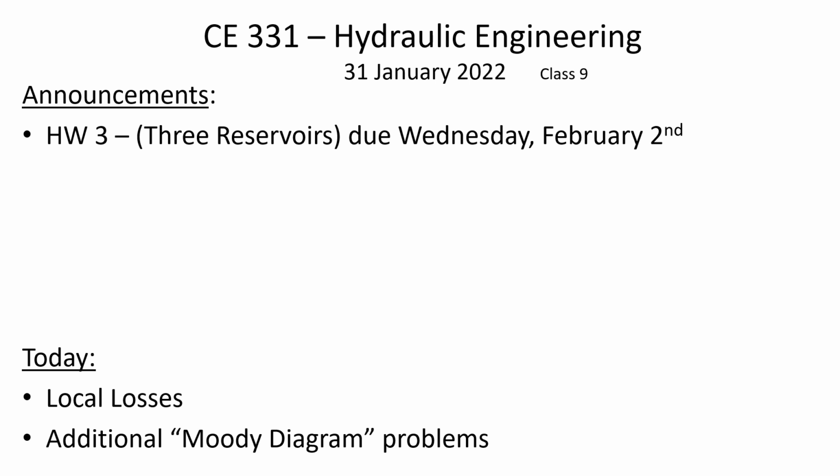Do you know why the solution from previous years wasn't the same or didn't work in that? Well, I think that normally in previous years I would do the problem with the Darcy-Weisbach equation, which we did, and it solved fine. But when I did the Hazen-Williams equation in the past, I didn't use goal seek. I was just sort of keying it in by hand. And so I think it's because I was throwing the goal seek in rather than the by hand iteration. That's all I can figure.